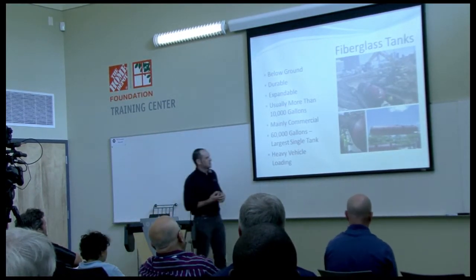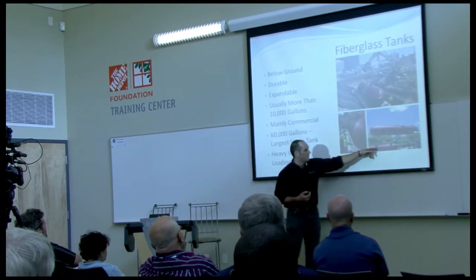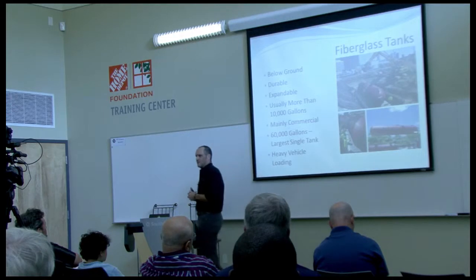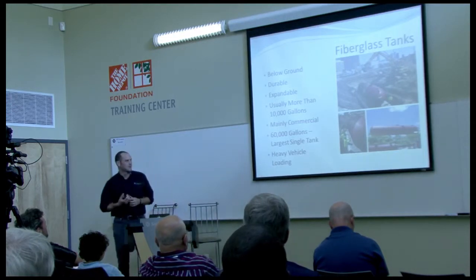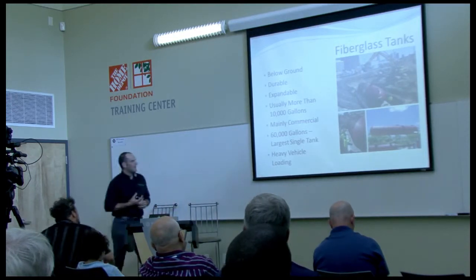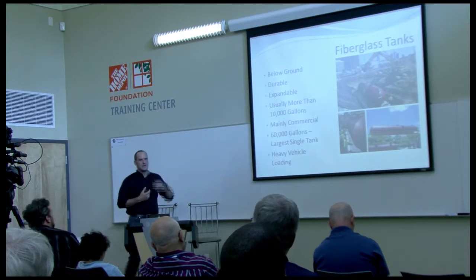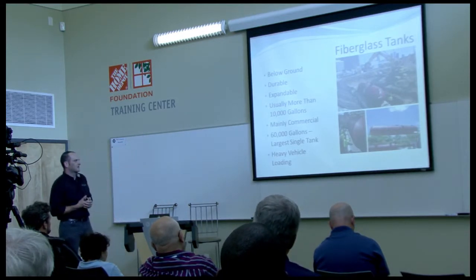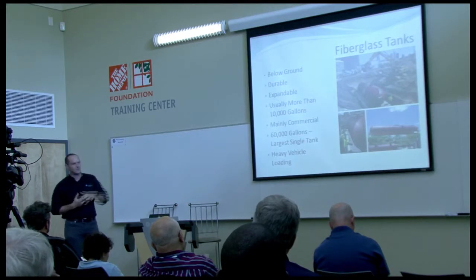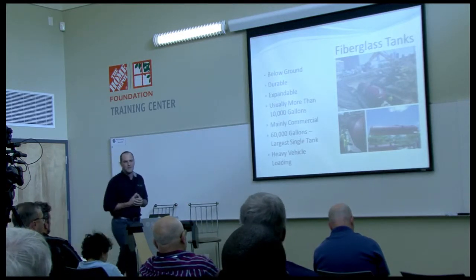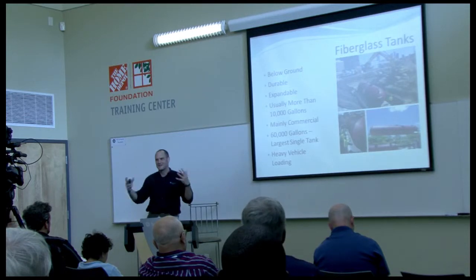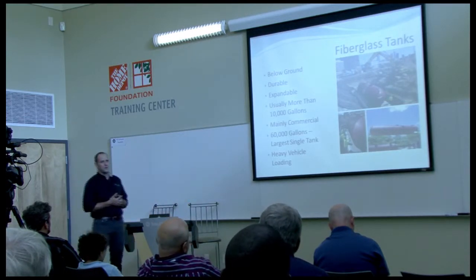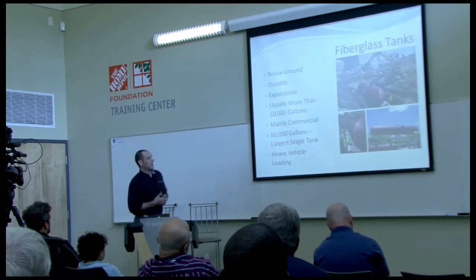The bottom right picture, you can't really see it, but we had three 15,000 gallon tanks linked together for a single 45,000 gallon system. That was at the University of Miami. Generally, you take a pretty heavy leap forward in cost when you go to a fiberglass tank. They're made to order, so these tanks are not sitting on a yard somewhere waiting for your order. You specify the inlet size, the outlet size, the manway, all that stuff. So generally they're quite a bit more expensive, but they are very durable.